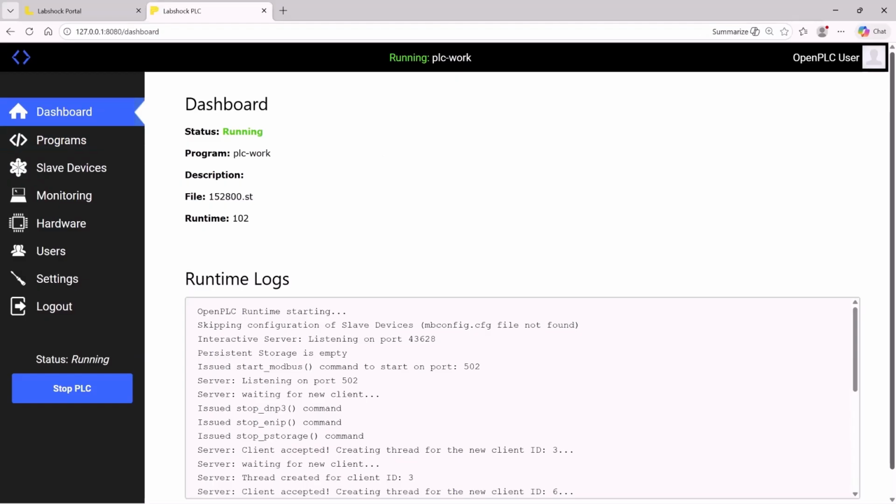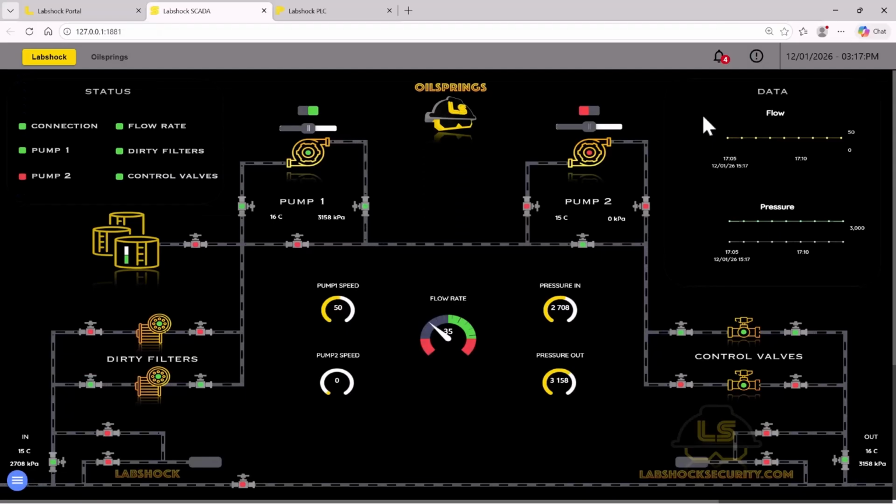And then you can see in the lower left-hand corner, we actually have the option, like I said, when logging into a controller with the vendor software, to click here to stop the PLC. Now, in this case, remember that the PLC drives the process, which in turn also drives the SCADA or the monitoring or the HMI interface that we have. It's monitoring and controlling the environment because the HMI is pulling that data from the PLC, which in turn is pulling it essentially from the sensors that we have out in the field.